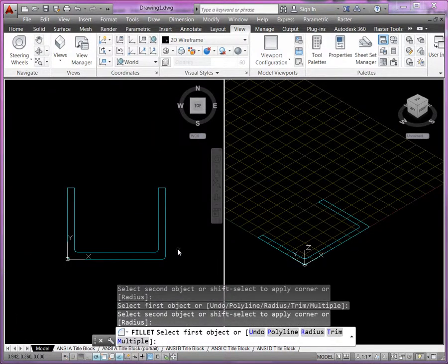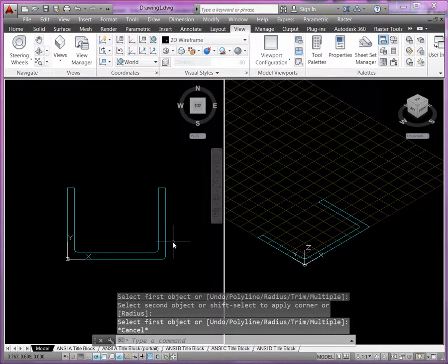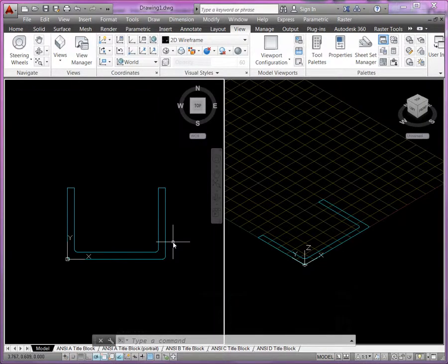Great. So if you think ahead and take a look at the solid model, try to understand what's the basic shape, what's the basic form, what are the main profiles that I can use to drive the main shape and form, and incorporate your sketch tools to be able to create that profile either as a closed polyline or a collection of lines that are converted to region. Again, we'll talk about that later.